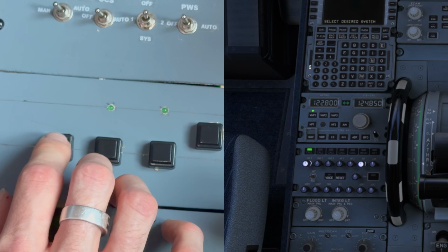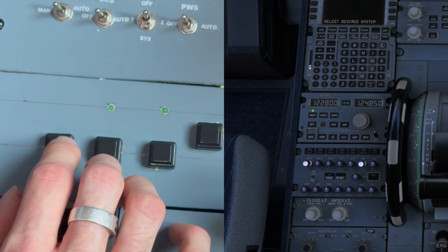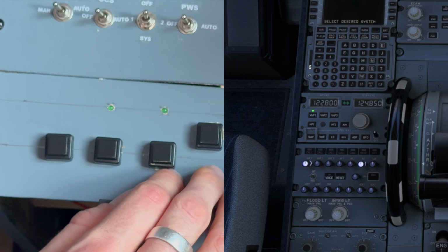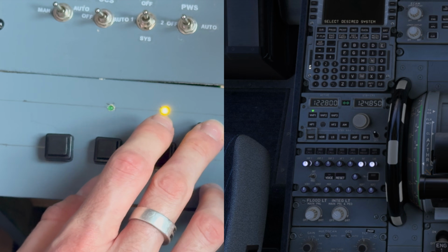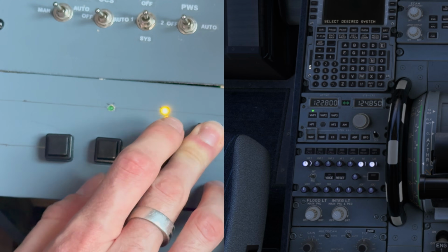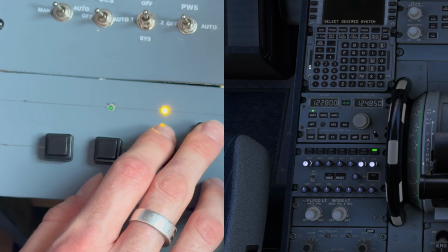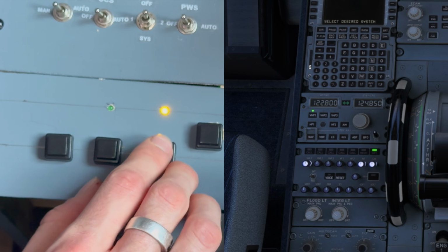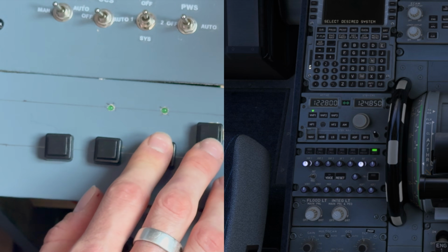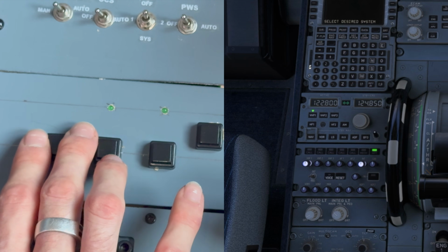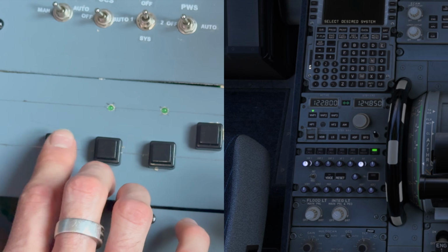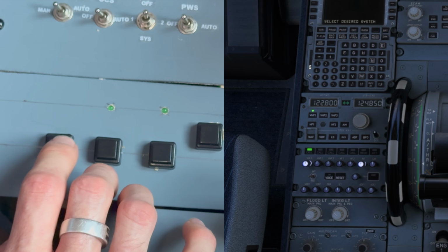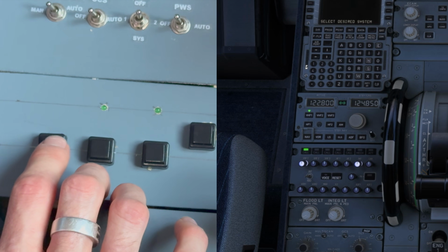So the reason why I wanted it to go onto the VHF1 call is so typically the cabin call, say they're ready for departure or whatever, so we click cabin and then we answer the call, so the ATT light begins to flash, so we answer ATT, and then after the call we've finished the call, so we can turn off the cabin, and then we press reset. Now notice the ATT light is still on over the cabin, and we want it back onto VHF1 to communicate with air traffic control. So when I press the reset button, it just flicks it back to VHF1 as well as resetting. So that's what we want.